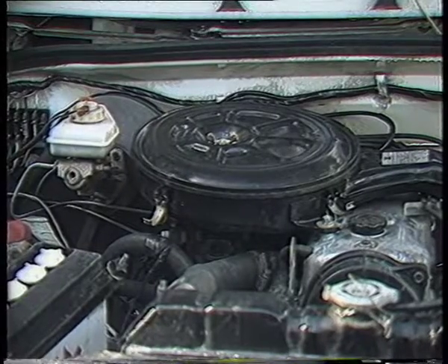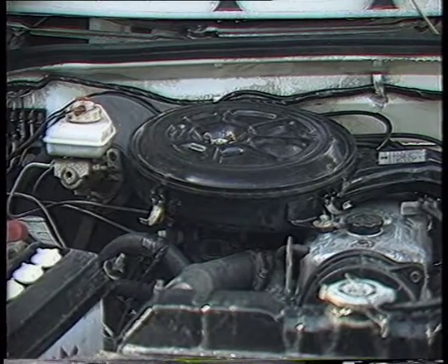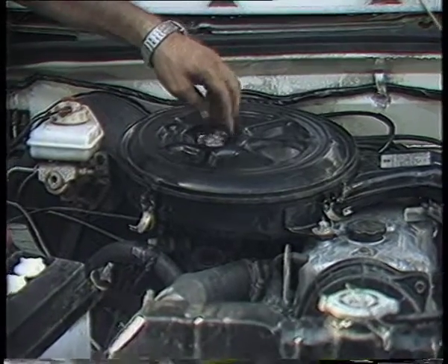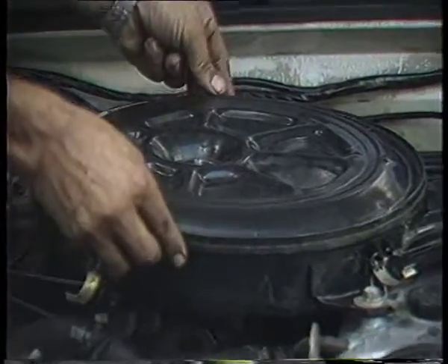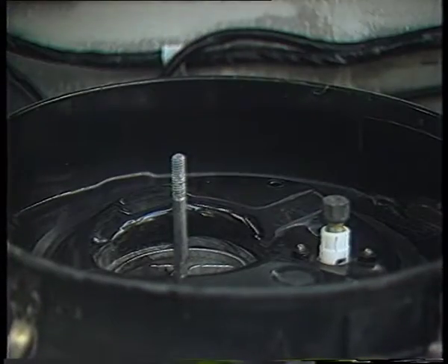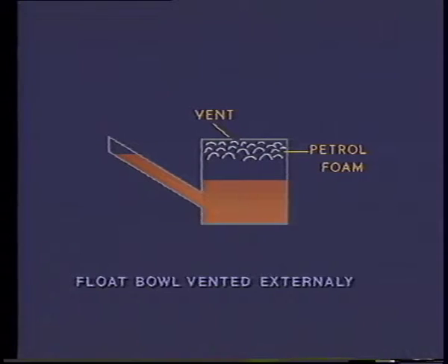Any discussion on carburetors would be futile without discussing the air cleaner of a vehicle, which protects the engine from abrasive matter, silences the air intake, and operates as a flame trap in the event of blowback. As already discussed, with a float chamber vented directly to atmosphere, a progressively rich mixture is produced as the filtering element becomes clogged.